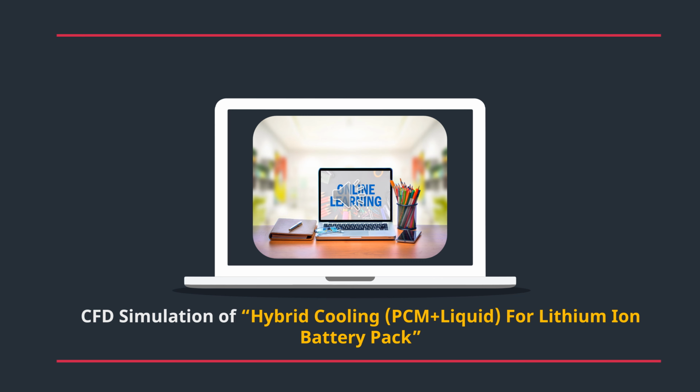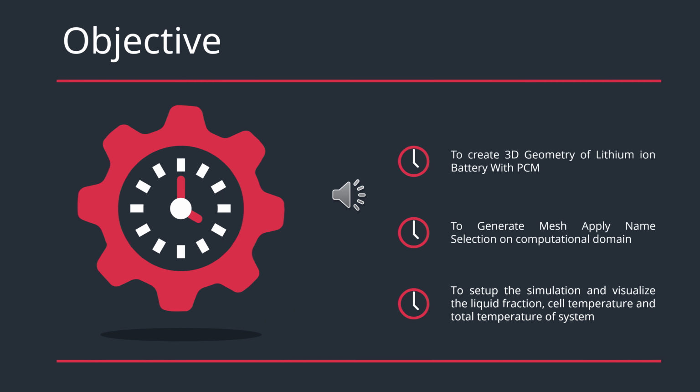CFD simulation of hybrid cooling, PCM plus liquid, for a lithium-ion battery pack. Today's objective is to create a 3D geometry of a lithium-ion battery pack with PCM, generate the mesh, apply name selection on the computational domain, set up the simulation, and visualize the liquid fraction, cell temperature and total temperature of the system.